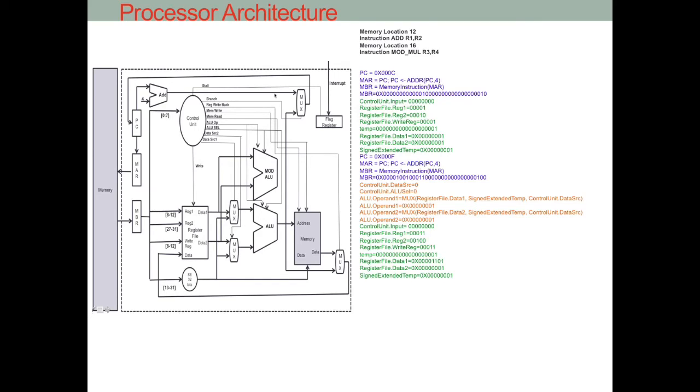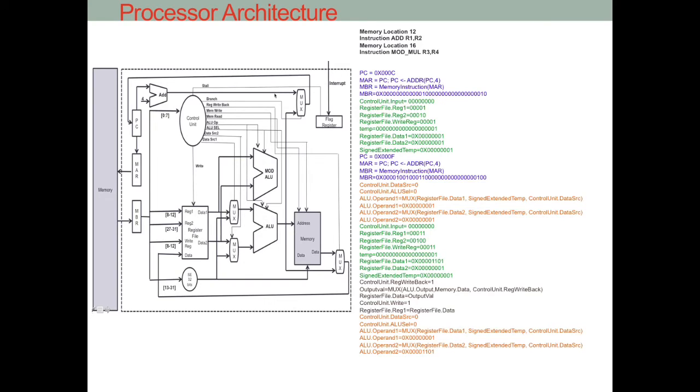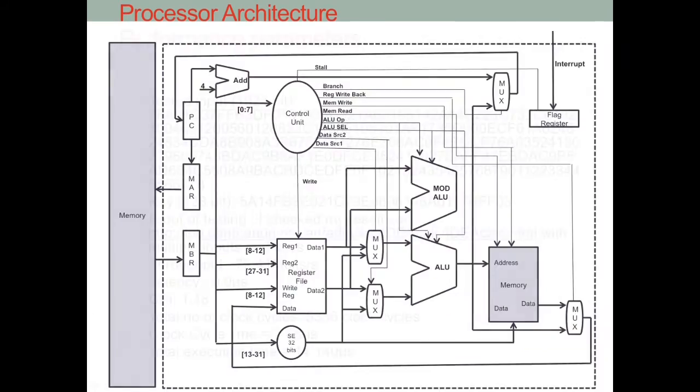Then it enters the memory access stage and the next instruction enters the execution stage. In case of a load store instruction in displacement and immediate addressing mode, the memory will be accessed, otherwise the instruction will go to the write back stage, where the result from the ALU will be written back to the register file destination register R1, and the next instruction will move to the memory stage and subsequently to the write back stage. So this is how my 5-stage pipeline is working.